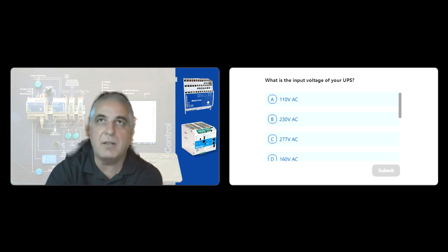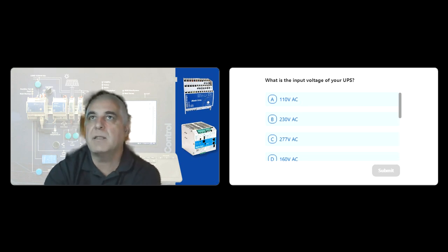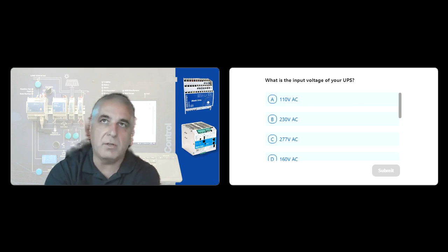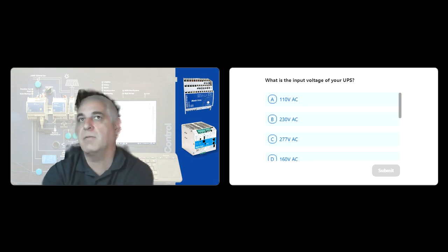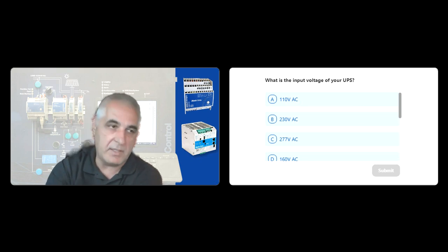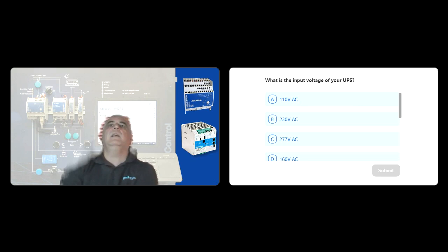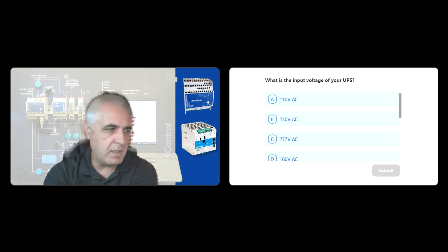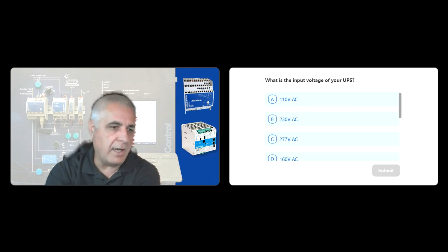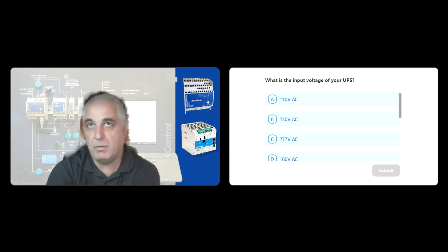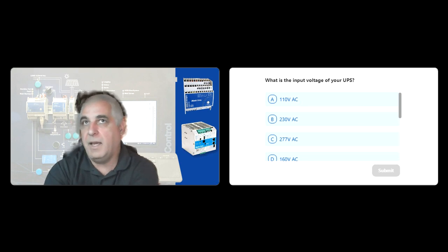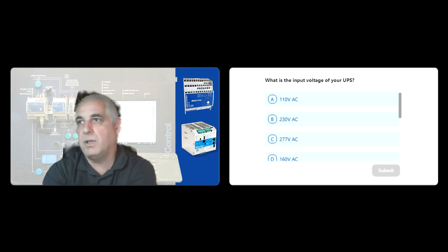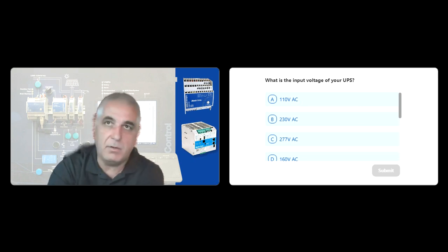Probably 40–50% of our DC UPS sales are because we have a universal input. And the universal, I mean truly universal, when people don't have to switch between 110 or 230 or 277. They can use it in any application. So that's basically very critical for many customers. Obviously, there's always the local guys who know they have 110 or they have 230, and they're just looking for that. For those guys, it's more critical, the output voltage or sometimes temperature ratings or things like that.